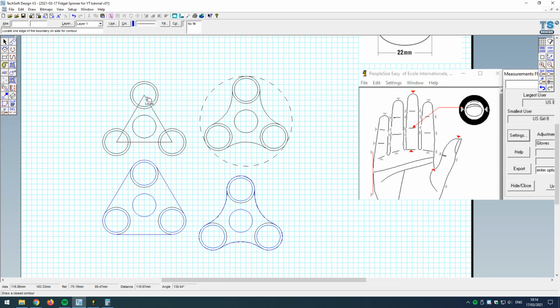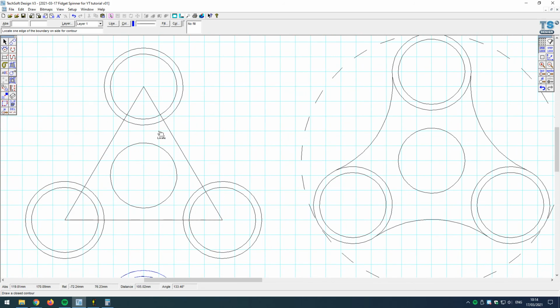Over here, now this is going to be a problem because look, the inside cutout is not going to work with this triangle. Let's just do that cutout there. I think in this particular case, I'm going to have to change my plan a little bit. Let me think about it. Yes. I'm going to have to trim that line there, that line there, and that line there. I'm hoping this is correct. Then I'm going to contour. Let's just think about this.